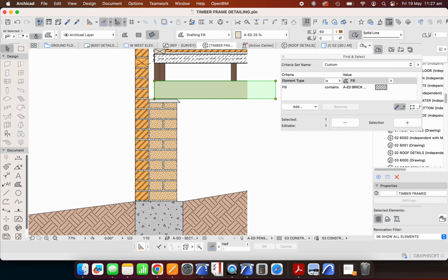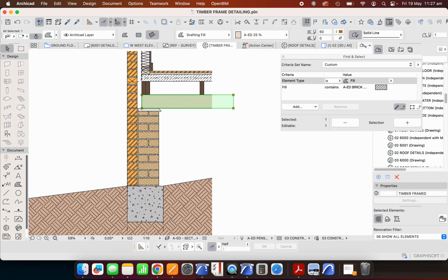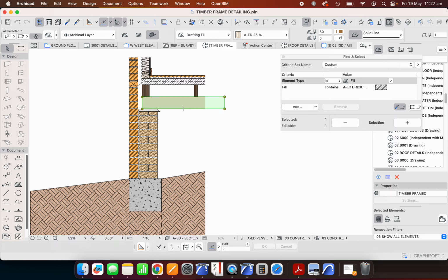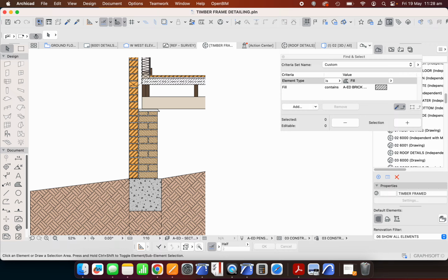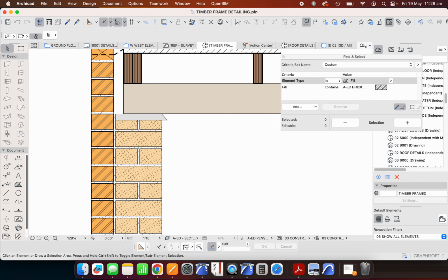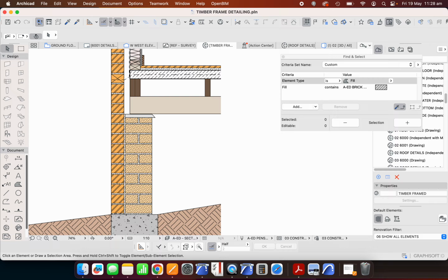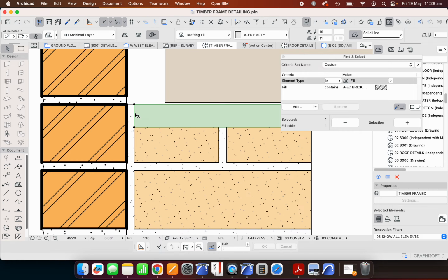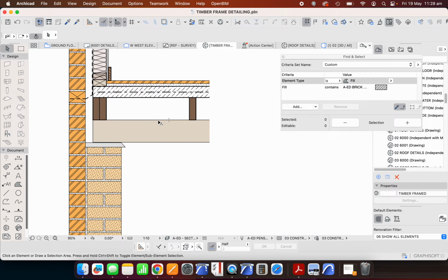Now, hopefully they can't do it. Hopefully they're not going to want to do it. But the idea is that if we inspect a subfloor, and this is, of course, one of the biggest issues with subfloors, we need to inspect them. If we regularly inspect it or get a pest person to inspect them, then we're going to see the line of termites going from the brick up to the timber. Because the problem is that they could crawl through the middle of this brick pier and we'd never see them. Or they could crawl between the gaps between this brick and this brick into the timber and we'd never see them. So the idea of the ant cap, and of course the ant cap needs to go all the way to here, is that we're going to be able to see it happen if it's happening.